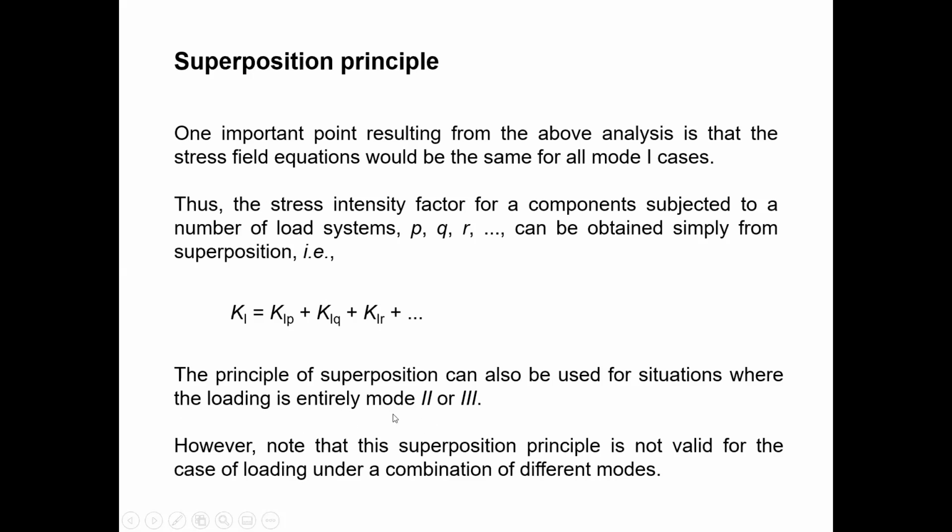If you have mode 2 and mode 3 also, we can use that particular theory. But for a combination of different modes, we cannot use that. For mode 1, the opening mode, with bending and torsion and axial loading, we can use the superposition principle. But for opening mode, tearing mode, and sliding mode combinations, we cannot apply the superposition principle.